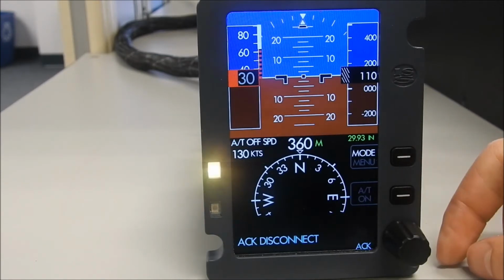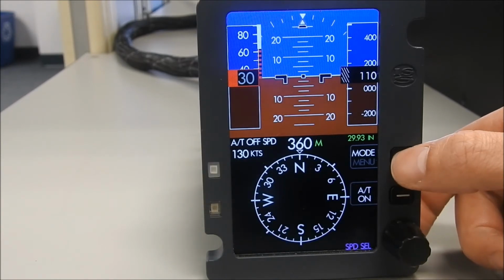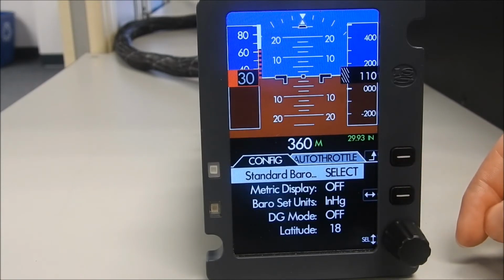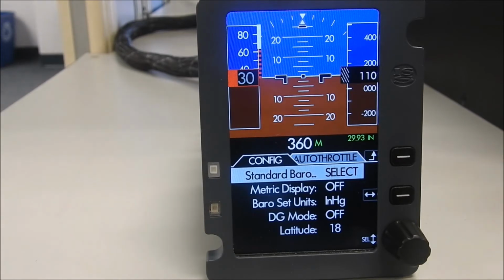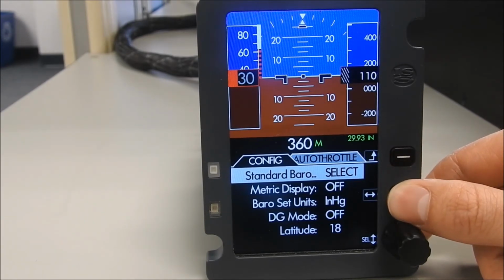To access the integrated standby unit menu, press and hold the mode menu key until the key zooms up, and then release. The integrated standby menu will appear on the bottom half of the display. It can be exited by pressing the top key, or paging between menus will occur with the bottom key.